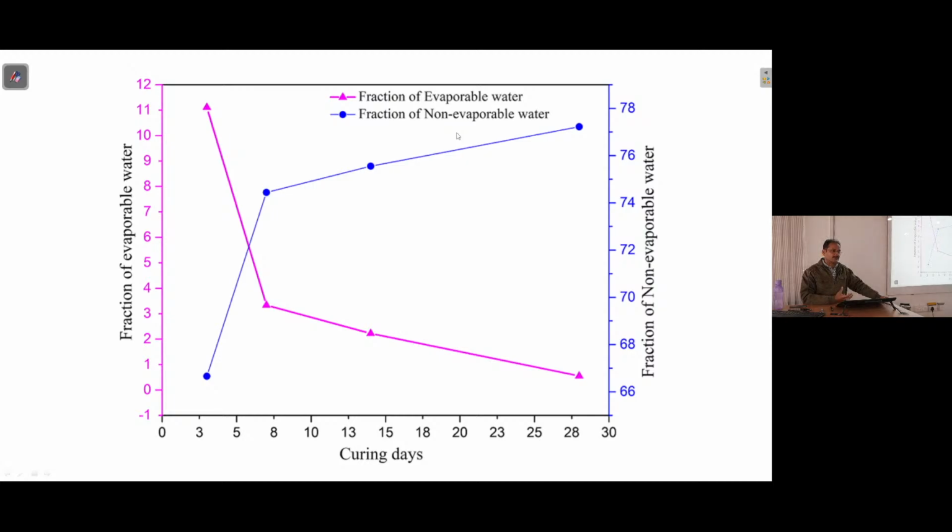But grain growth I think is the simplest thing to visualize. Grain growth occurs after recrystallization, if you remember, right? Then what happens at the grain boundaries, you have mismatch. Similarly here also, as this CSH gel formation takes place, it will grow in size at different locations after nucleation, and in between you will have some space which will not be filled, where the gel formation will not take place.